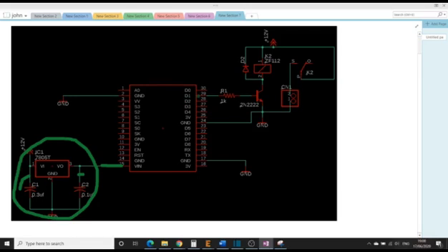And then we have the D1 pin, which is set as an output, and we have connected a 1K resistor, which is connected to the base of the NPN transistor. Just a brief explanation why we are using that 1K resistor. We are using it in order to limit the excessive current to the base, and also if the transistor is on, then the base voltage here is 0.7 volts higher than the emitter point here.